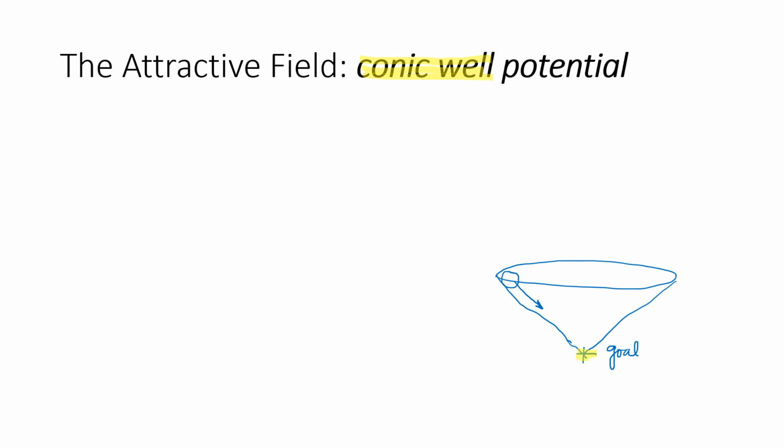For that, you can write down the expression in this form, where you have the attractive potential. Since we have defined that these robot manipulators are going to have multiple, or n, joints, and we have already defined the Denavit-Hartenberg coordinate frames for those, I can have a subscript i added to that.